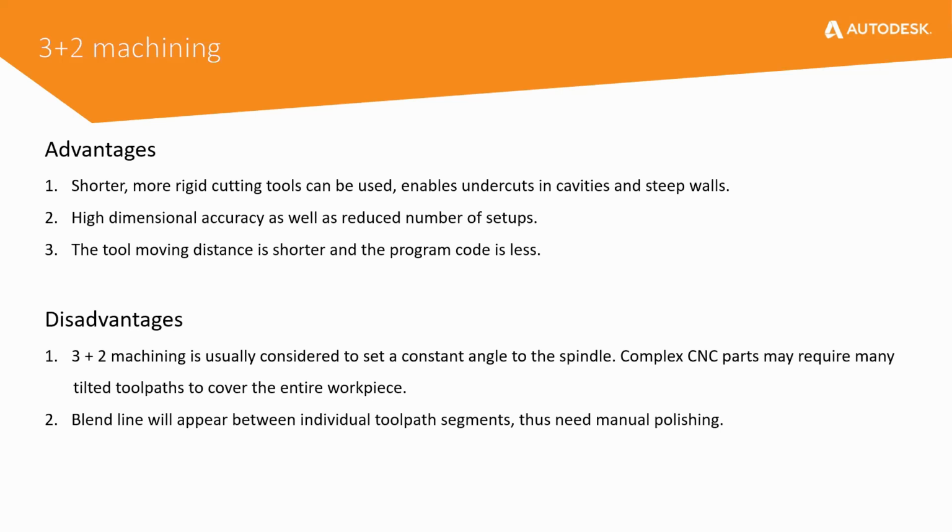Coming to the disadvantages, the user has to create multiple work planes and toolpaths in different tilted positions to cover the entire workpiece. Sometimes this will take more programming time as well as need a skillful programmer. Blend lines will appear between individual toolpath segments, thus needing manual polishing.